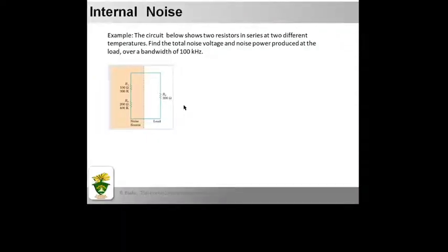Another problem here: the circuit below shows two resistors in series at two different temperatures. Find the total noise voltage and noise power produced at the load over a bandwidth of 100 kHz.